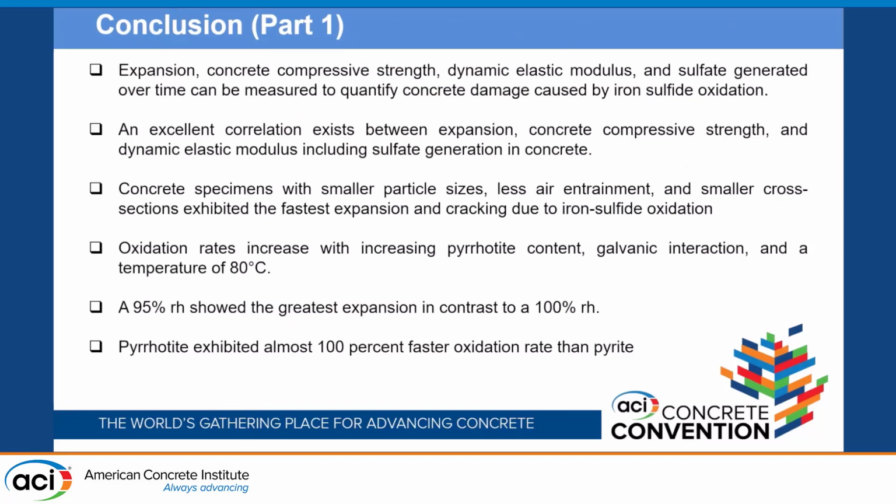The conclusion from my limited study: expansion, concrete compressive strength, dynamic elastic modulus, and sulfate generated over time can be measured to quantify concrete damage caused by iron sulfide oxidation. These four parameters showed an excellent correlation, and concrete specimens with smaller particle sizes, less air entrainment, and smaller cross-section exhibited the fastest expansion and cracking due to iron sulfide oxidation.